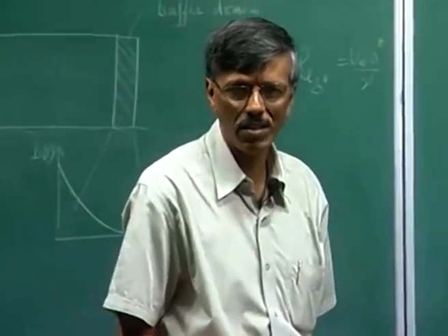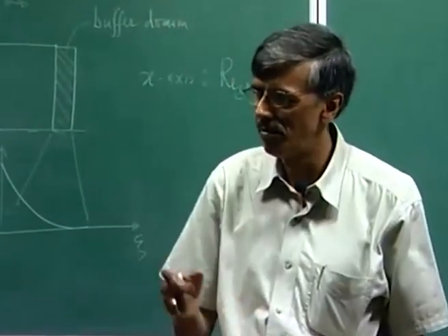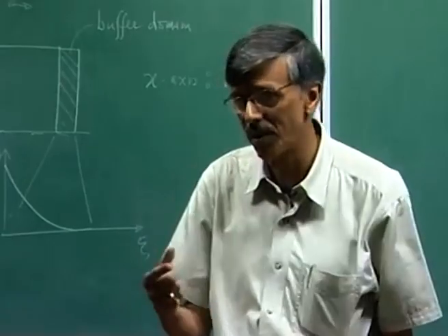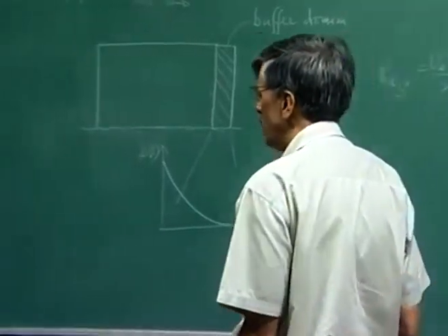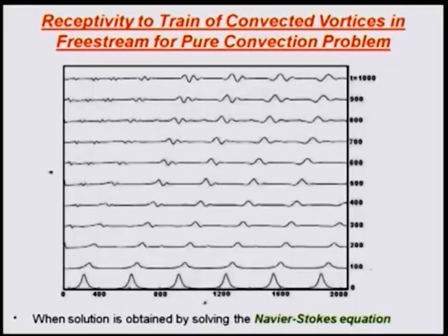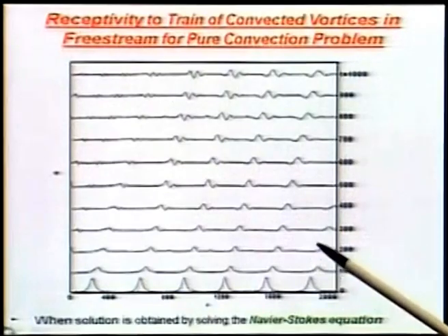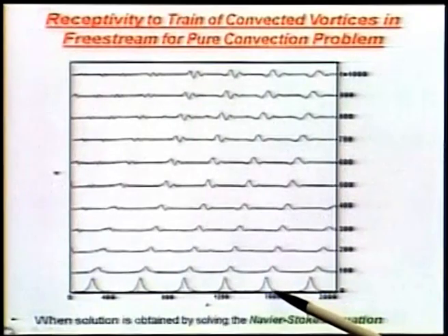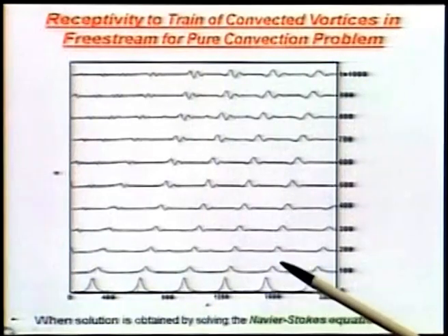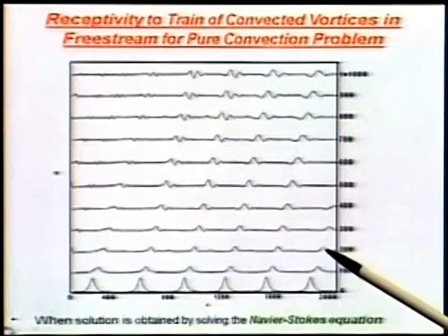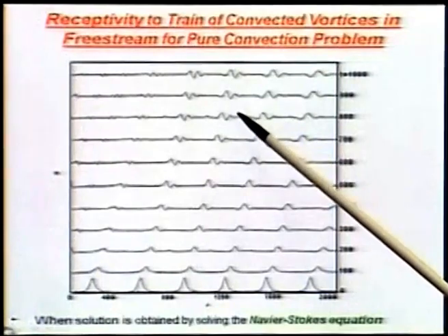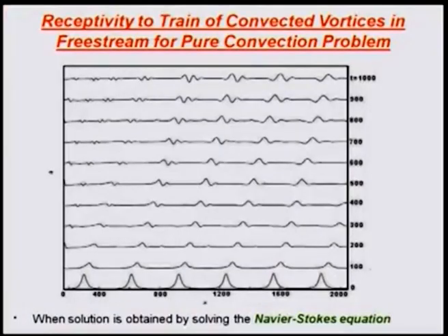If it is a periodic excitation, then I will have the excitation in terms of multiple frequencies. So, with time I am going to see that if I have a peak corresponding to omega naught, I will also have a secondary peak corresponding to 2 omega naught and 3 omega naught. That is what you are seeing. The secondary and tertiary peaks are coming up.